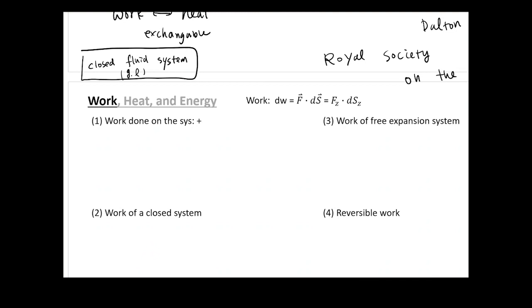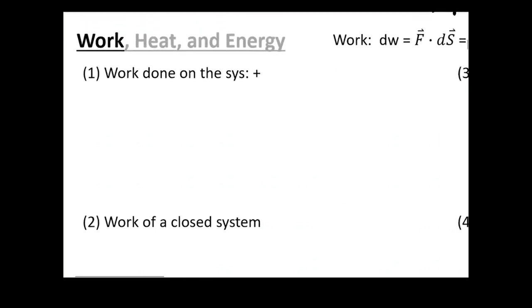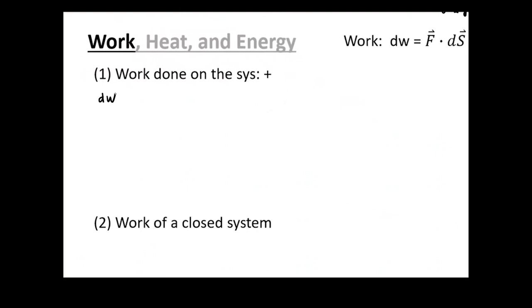Another thing you're going to hear a lot is that we're going to further simplify this fluid system into the simple system. Every time we say the simple system, that means when we talk about the work, it's only the PV work. Eventually, things you're going to deal with will be the closed, fluid, simple system. So no material exchange between your system and surrounding, and the work we talk about is only the PV work. So let's first discuss what is work.